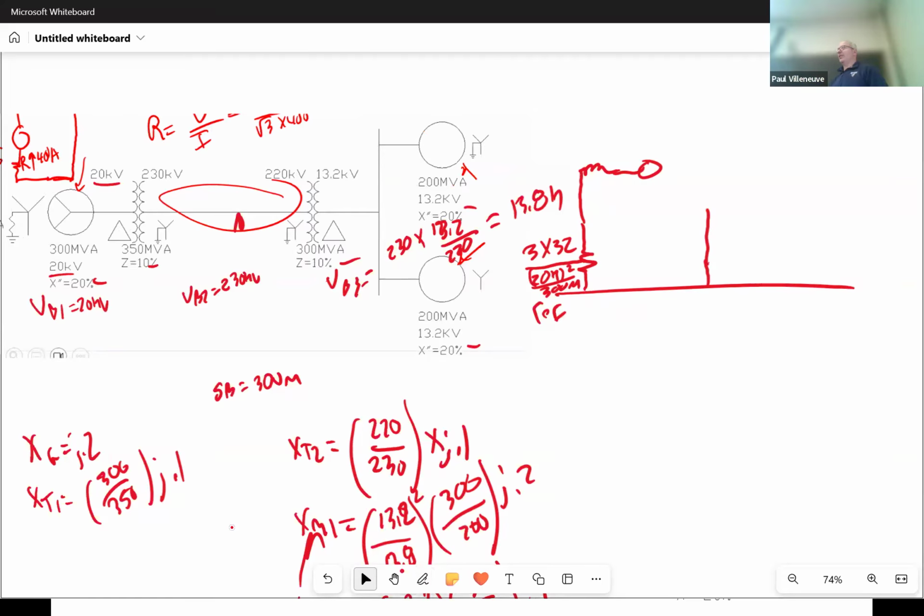Yeah, it can leave because it circulates over here, which allows it to exit or enter the transformer because that delta connection permits it. Remember, what flows on the primary has to be able to flow on the secondary. So I can circulate my current in my delta. Notice I said in the delta, not exiting the delta, but I can exit or enter the Y.